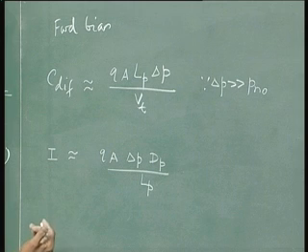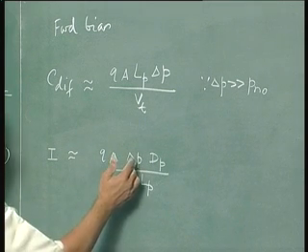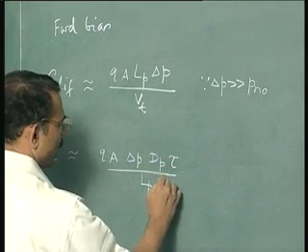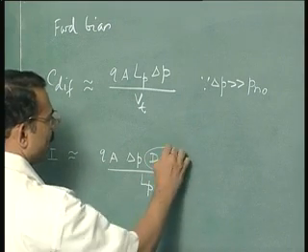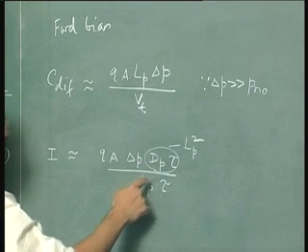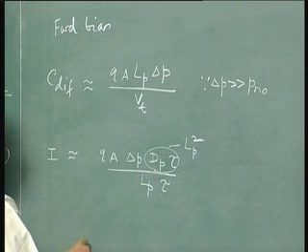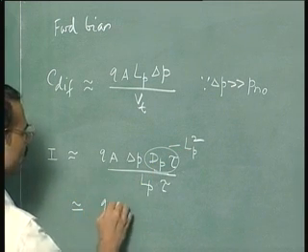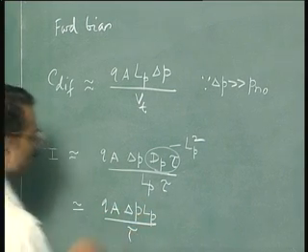So look back into the forward diode equation which we have derived, and you will find this equation. We can multiply by lifetime tau and divide by lifetime tau, and then we can identify this term as LP square. Now this LP square will cancel with LP, one of these LP terms will cancel, and so this is equal to Q A delta P LP by tau.